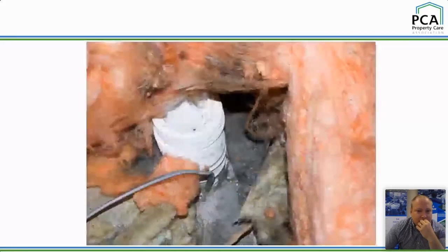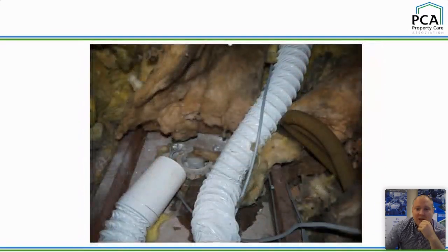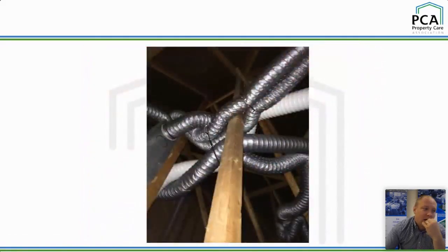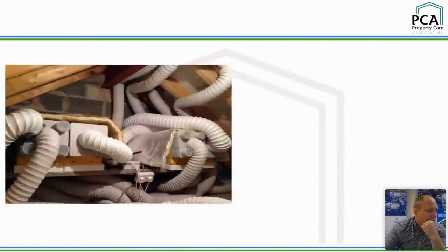Similar things. Again, check where the ducting's going. How often do you find that when you do some investigation, all that's happened is that the ducting terminates in the loft void, if it's even connected properly? And again, hopefully you're sucking through your teeth here as well. Similar thing, it's really going to reduce flow. So hundreds of these, the show could go on really.